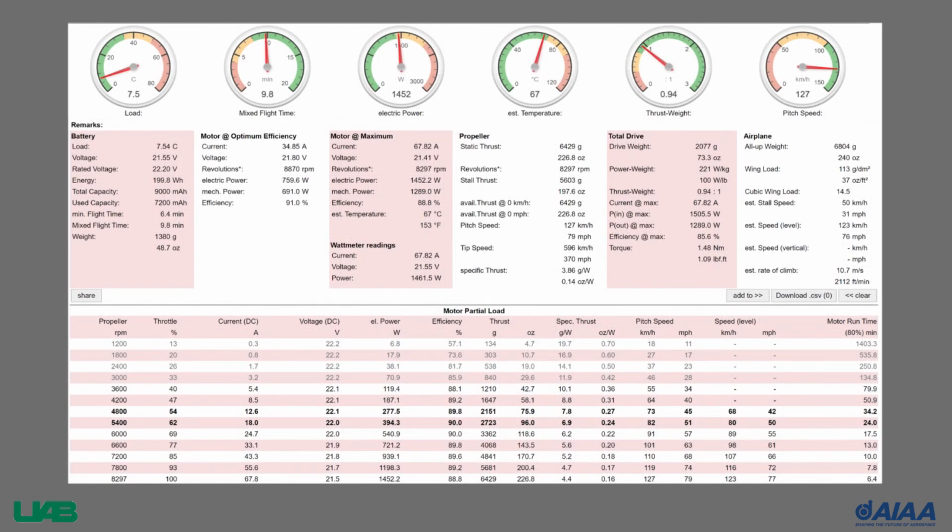The battery selection process prioritized reducing weight while still sustaining the desired flight time. Therefore, 2 6-cell 3200 mAh LiPo batteries in parallel were chosen. eCalc was used to assist with motor selection in addition to checking the flight time against parameters such as charge capacity and throttle percentage.